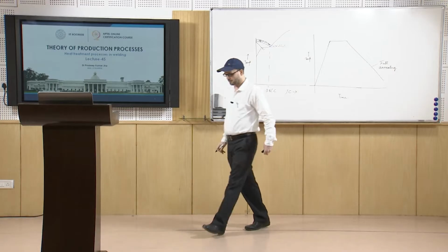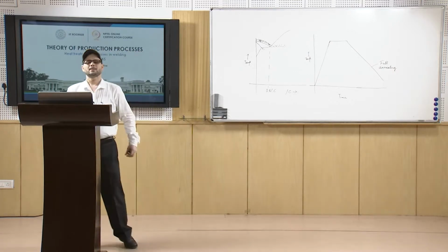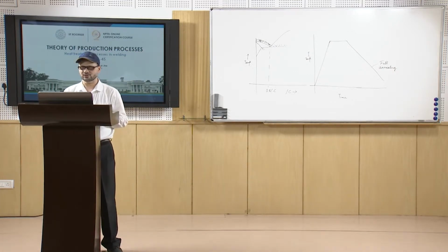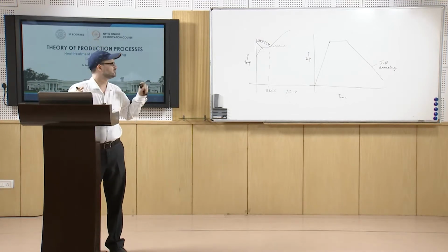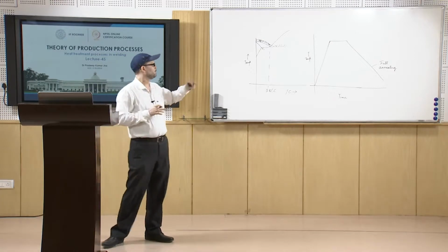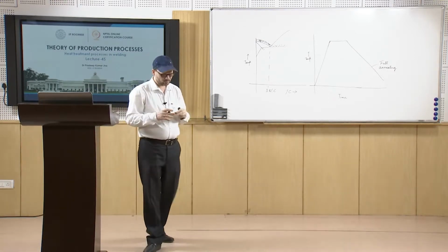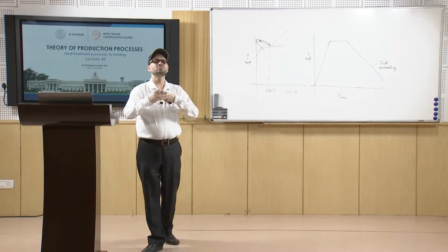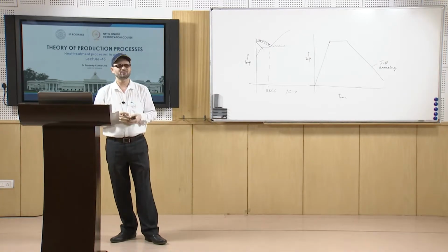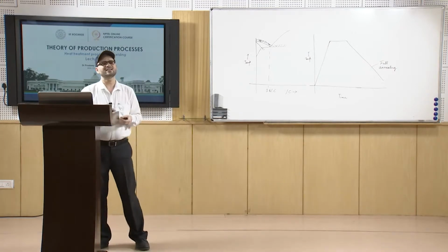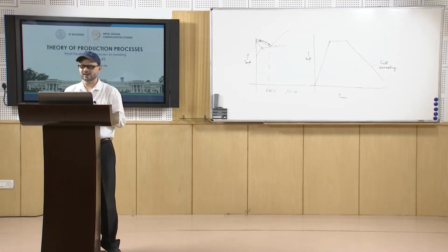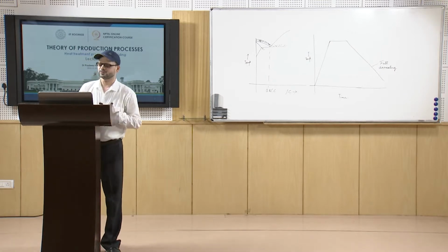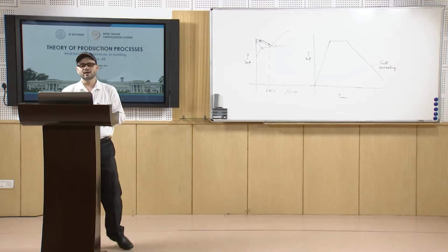So, this is the process which is known as full annealing, and this way the grains of pearlite and ferrite are formed, because normally annealing is done to relieve the material of stresses, to impart more ductility to the specimen, certainly at the expense of its strength and hardness.